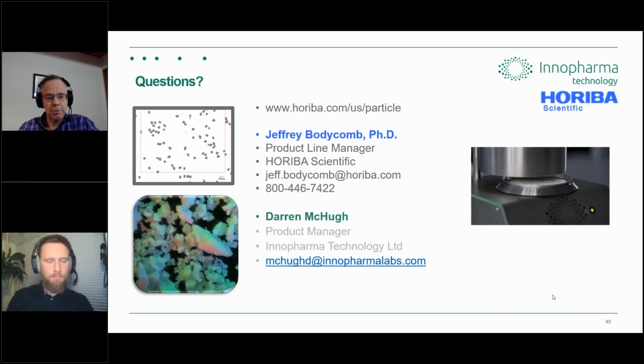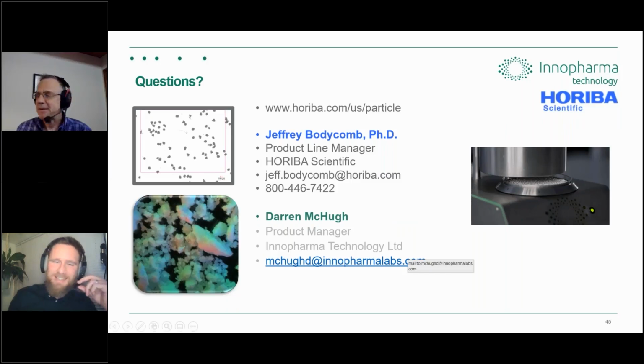Now, going back to Darren's comments, I have a half micron resolution, but if you hand me a 2 millimeter particle, that system won't get that resolution in any useful way because of the field of view. So your resolution is going to become coarser as your particle sizes get larger, just because of the trade-off between pixel size and field of view.